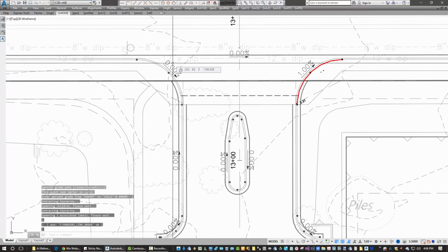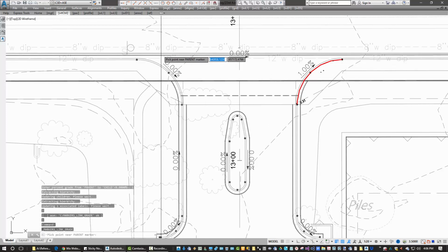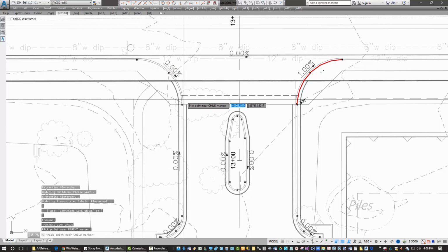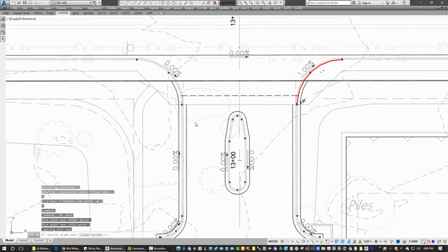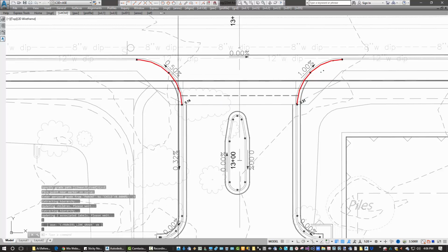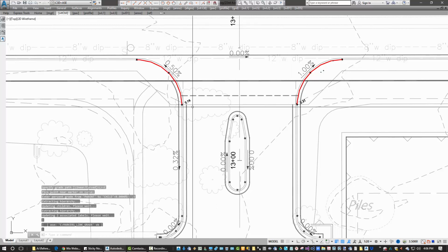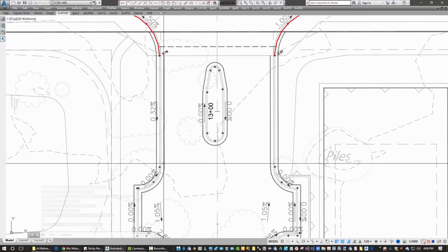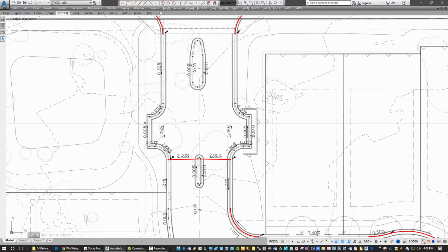One of these will be dependent and the other independent, depending on how the grading turns out. But we'll go ahead and start the existing elevations, and we'll adjust the values of our constraints as we move along for design. We'll take this one at 0.5% because we will be grading across the pavement here down into a low point that will likely be in this area.